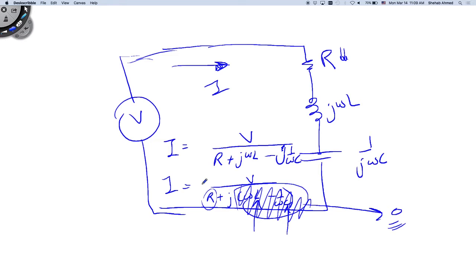It will be very large because I said R is very small and the voltage magnitude is the same, but the frequency just changed. So V over R will be a very large number in this case because I said R is small, and everything in parentheses disappears. So the resonant frequency for this circuit, in this case, was 20 kilohertz, if that's what caused this bracket to disappear, right?